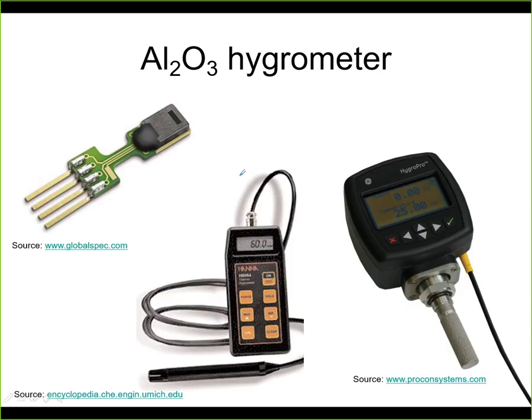Here is an example of such humidity sensors. So this is the sensor itself, so this is the opening where you allow the humidity to actually enter into the chip. In the chip you have electronic circuits that evaluate the changes of capacity and resistance, and they produce an electric signal. Some humidity sensors have an analog output, so then you can have voltage or current that is a function of the humidity.